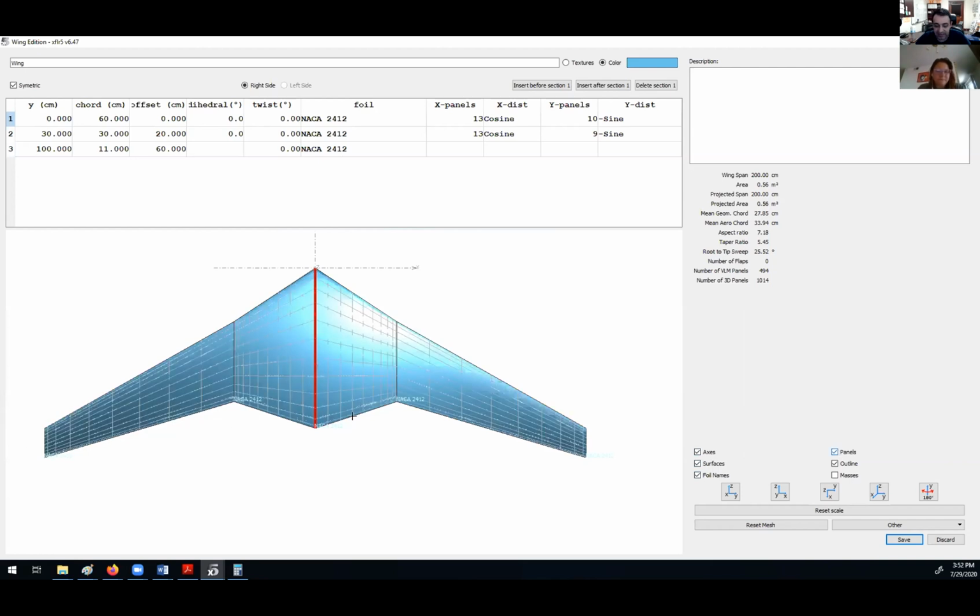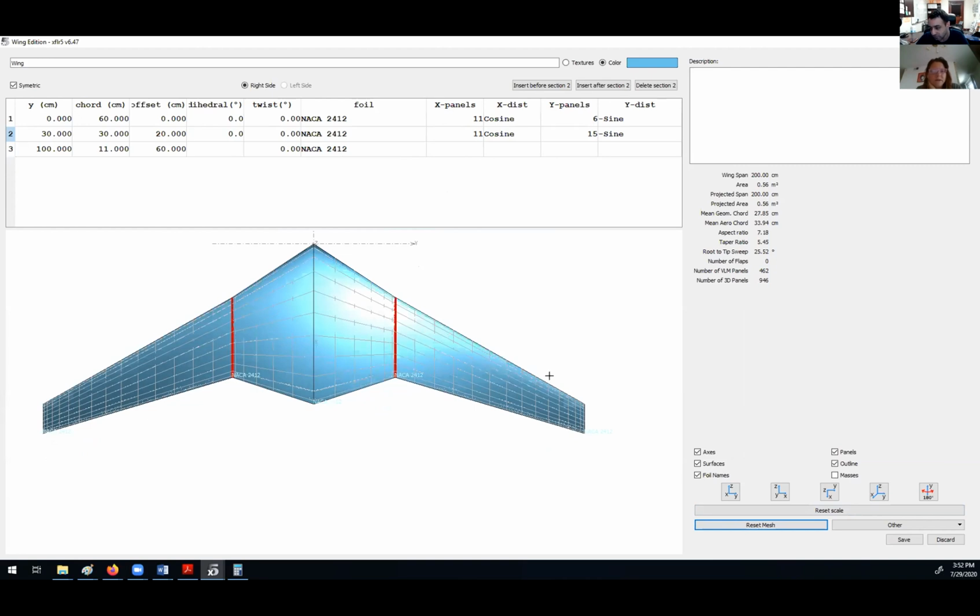This is a panel. This panel is important because the aerodynamic analysis is CFD modeling, using computational fluid dynamics. It makes the wing as small panels, runs the analysis on one panel after another, and does the integration. But here, usually it's better to apply a reset mesh. Once you apply a reset mesh, the software selects the best panels, the best size, for your analysis.